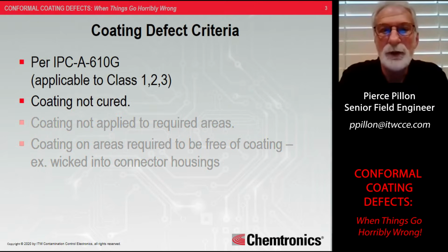An example of this is silicone coatings. Many silicone coatings are RTV coatings, polymers, room temperature vulcanization. And as such, they require a minimum amount of moisture to initiate that cure mechanism. So let's say you're in Phoenix in the middle of August, and the relative humidity in the facility is essentially nil.